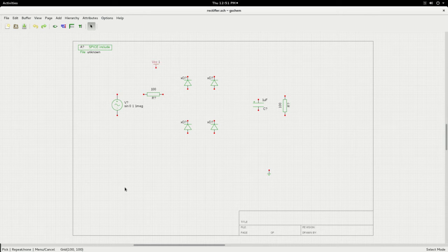Okay, this we will leave it for now. Now let us draw the wires. The wires can be drawn using this add nets. So click on that. Now you are in the add net mode. You will see that it searches and links to this net. Now I will start putting the wires.